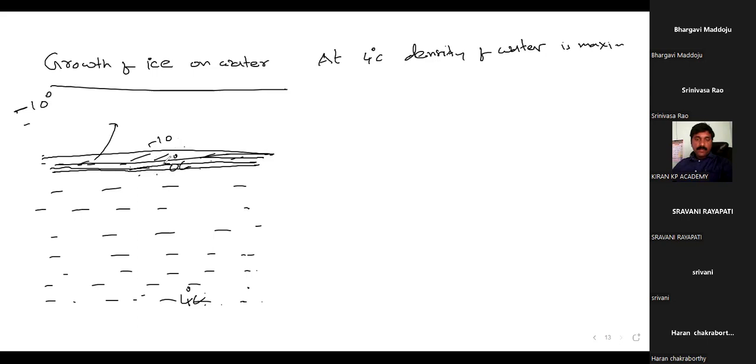But ice is a bad conductor. Once some thickness is formed, very little energy will flow from the inside to the outside. As time passes and the thickness increases, the energy travel from the inside to the outside is very low. The rate of heat flow decreases to a very low value.